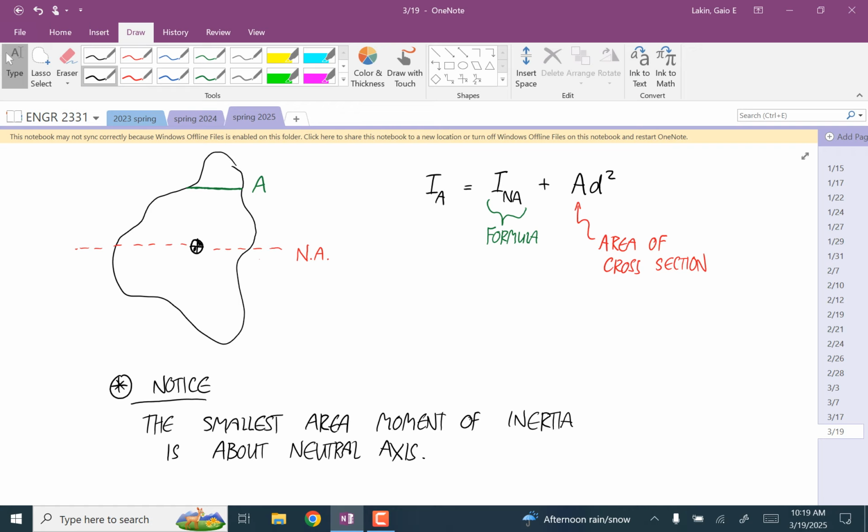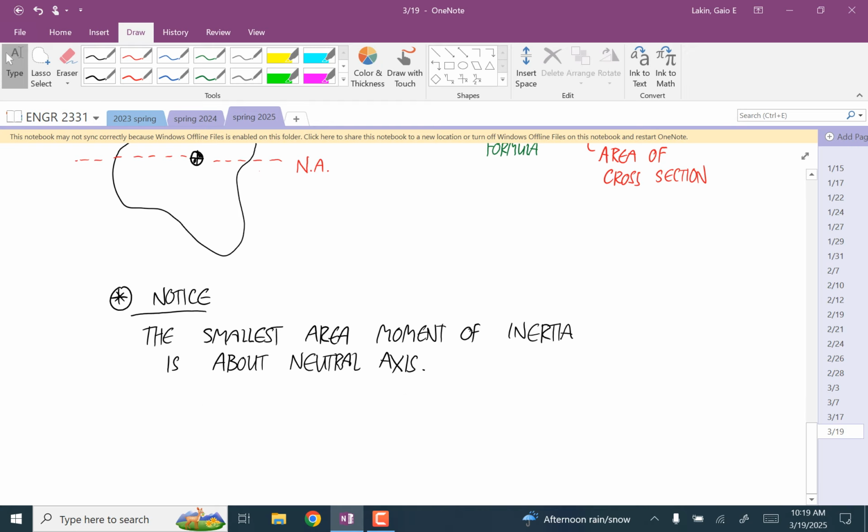Because we calculated, I gave you formulas for, the area moment of inertia of these shapes about their neutral axis. And the formula that we're using for stresses deals with the moment of inertia about the neutral axis. So why would you ever need to do it somewhere else? Well, it's if you're adding or subtracting shapes.